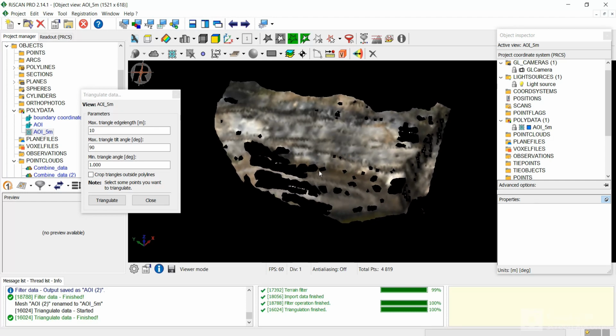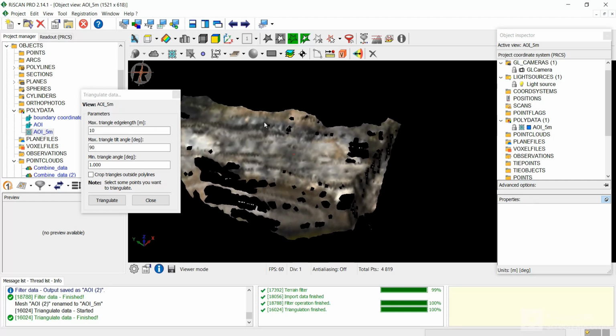So in order to fill these holes, what we have to do is click on selection mode and select the holes of similar shape. I have already told you how to select by clicking and creating a polygon around that hole, and when you are convinced that the entire hole has been selected, just right click to finish the selection.